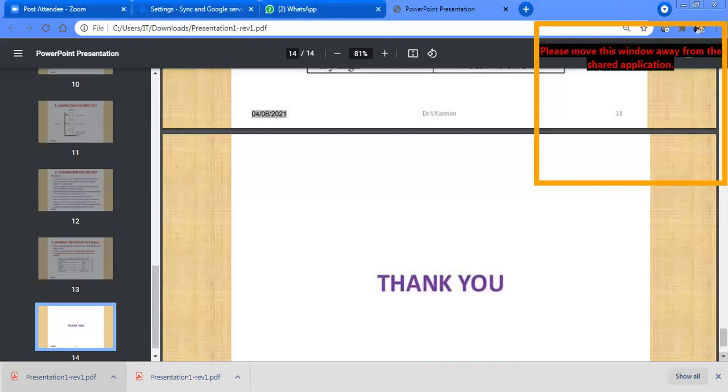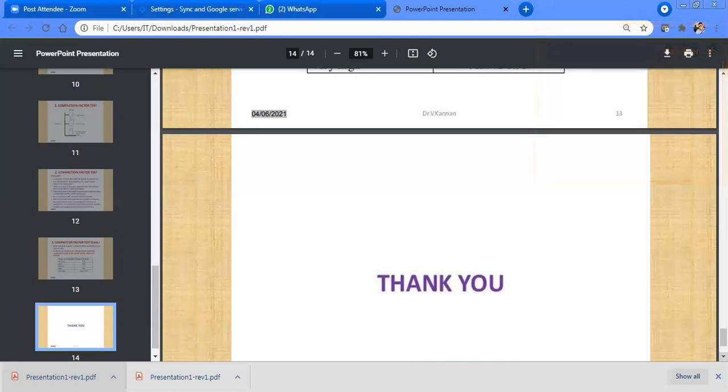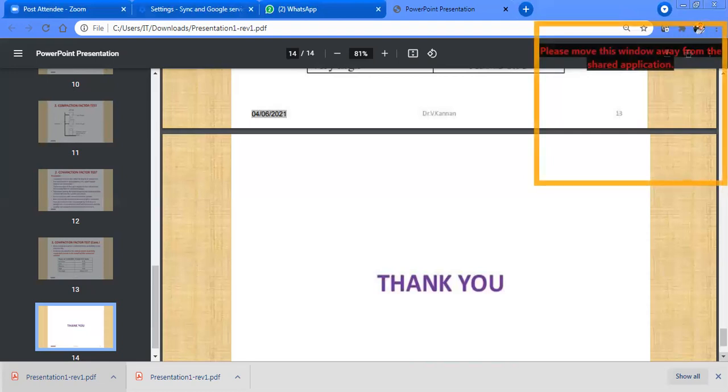When the quantity is up to 30 cubic meters, we will take 6 cubes. If it exceeds 30 cubic meters, we will take another 6 cubes to check the strength, durability and workability. What I'm saying is not hard and fast. Maybe it will be different in different areas.